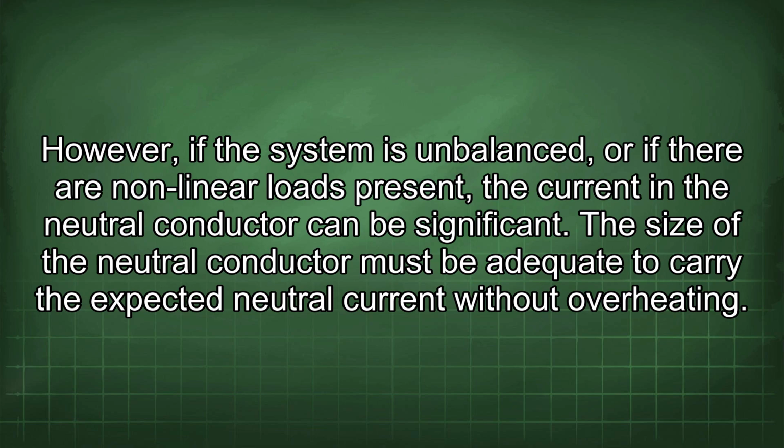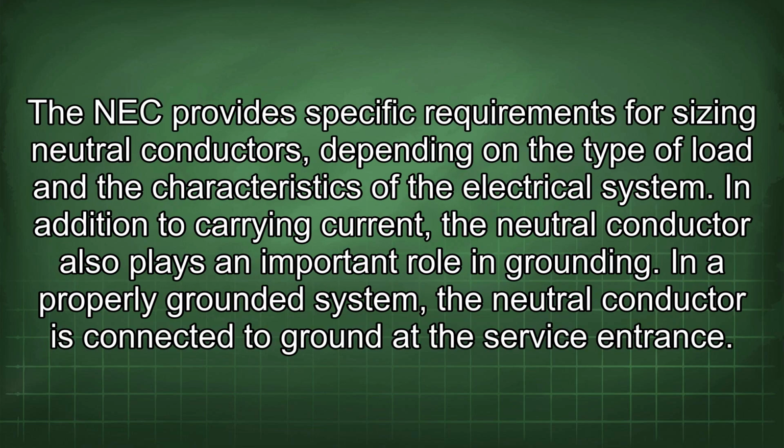However, if the system is unbalanced, or if there are nonlinear loads present, the current in the neutral conductor can be significant. The size of the neutral conductor must be adequate to carry the expected neutral current without overheating. The NEC provides specific requirements for sizing neutral conductors, depending on the type of load and the characteristics of the electrical system. In addition to carrying current, the neutral conductor also plays an important role in grounding.